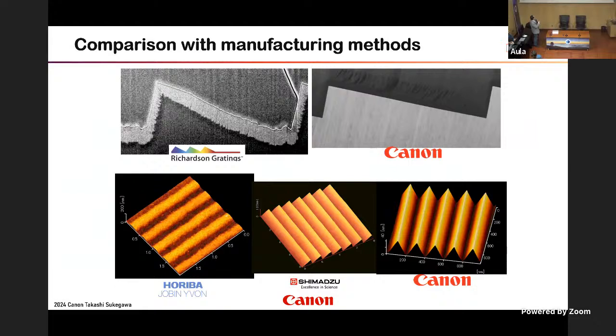They are focusing on the groove surface, meaning the blaze angle and blaze facet are important for the grating. So their quality is very nice. But you can easily see that machining removes the old material, so you can shape not only the blaze facet but also the counter facet. Some polarization characteristics show very good agreement with calculation for this kind of shape.